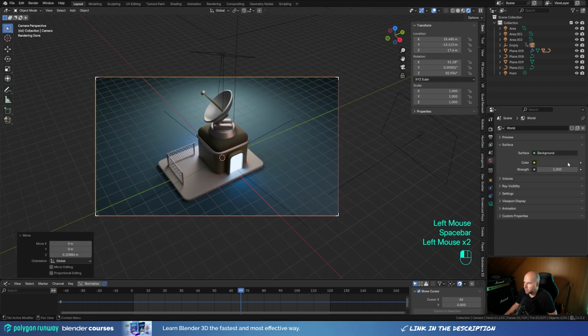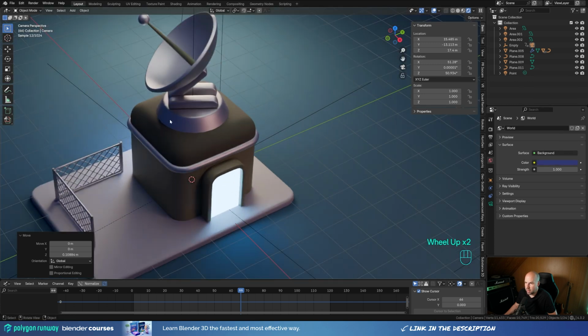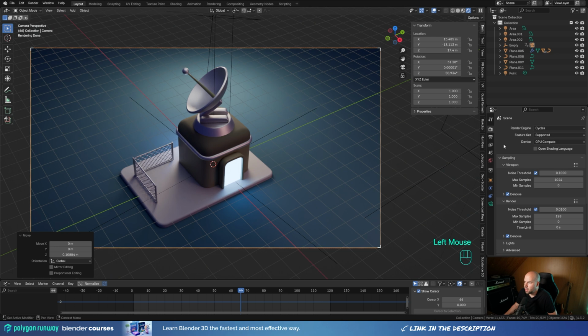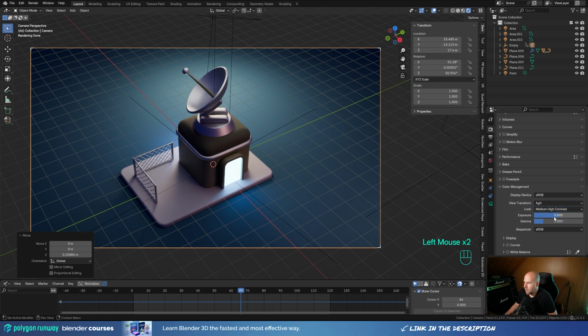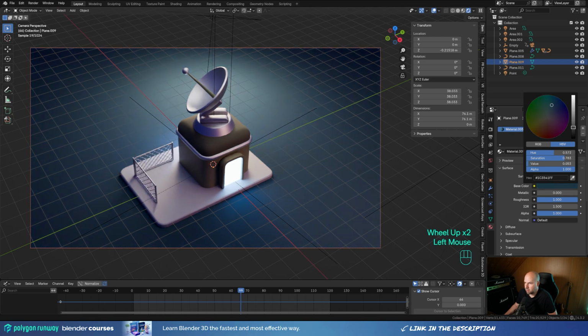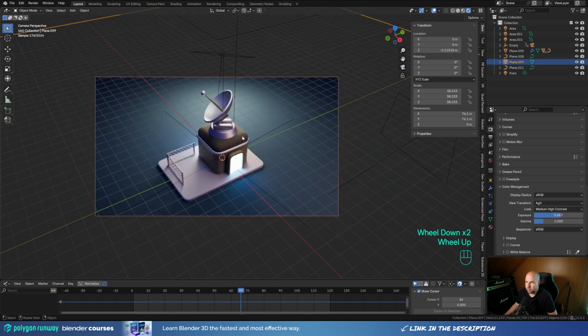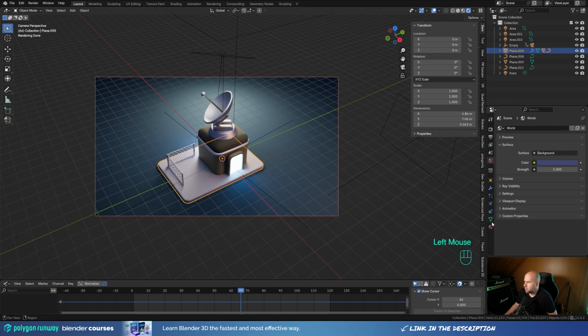And then in the world settings, you can always add some ambience around and color it as well. So you'll see how these shadows get that color tint, and it nicely blends those colors together. And finally, in the render settings, color management, you can add a little bit more contrast with the contrast settings. And if it's a little bit too dark, then add an exposure. And I will darken the background a little bit because it's now too bright, and go back and adjust this exposure for the rest of the building and play with the overall contrast. But I think this looks quite nice. Maybe this is a little bit too saturated, so let's try more subtle values, and maybe this needs to go a little bit darker.